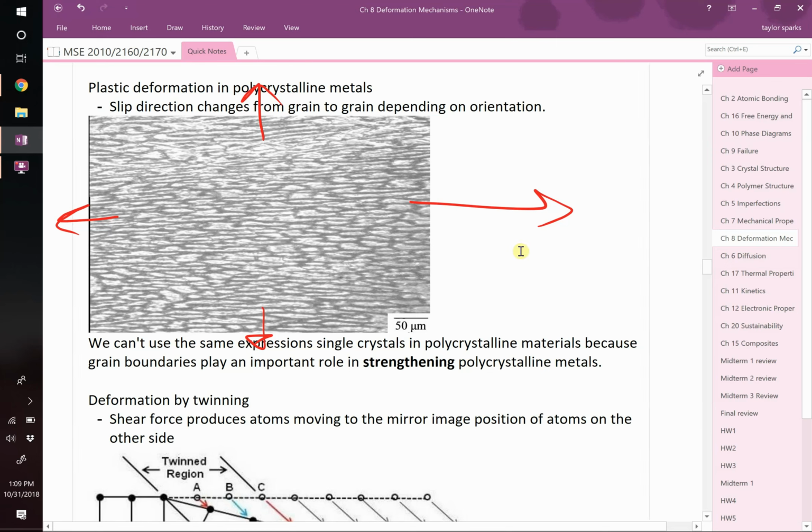So you can get polycrystalline materials that kind of look like single crystals in their behavior, in that there are differences. And you can actually go through a process called texturing, where you make a polycrystalline material, through a series of processing steps, look more and more like a single crystalline material. This becomes really important for electronic properties. Like later in chapter 12, we'll learn about piezoelectrics. These are things that are just amazing. But if you had single crystals, they'd be the best, and those are too expensive to make. So instead, they make them out of polycrystals, and they align the grains. They make them really elongated, and then they line them up. And the way they do it's pretty cool. We'll get to it later.